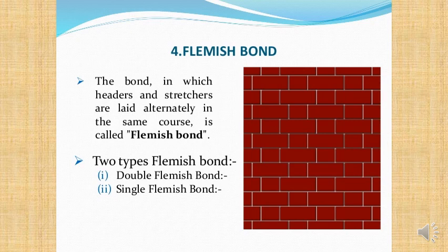One of the disadvantages of the Flemish bond is, like the English bond, you have to make sure that the wall is at least one stretcher length thick, and the header bond too. And so the wall has to be of a certain thickness, and that basically limits certain applications for this. A lot of villas wouldn't want to have an English bond, header bond, or Flemish bond because it makes the room smaller if the wall is thicker. And so that's why I think the stretcher bond these days is probably the most common.